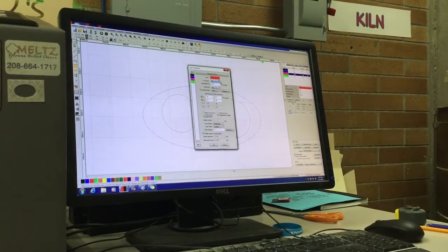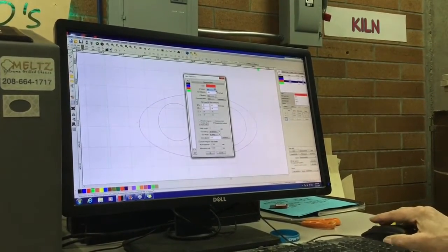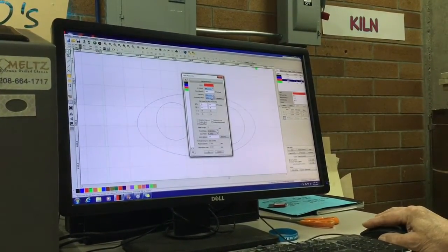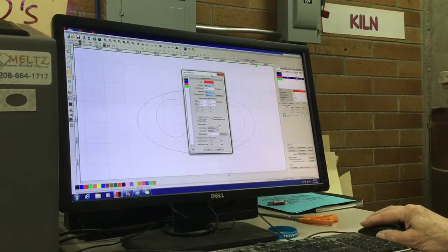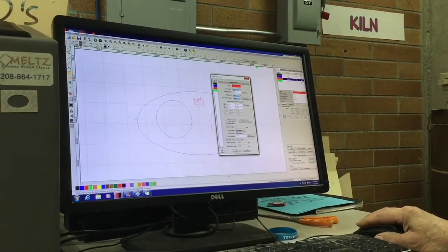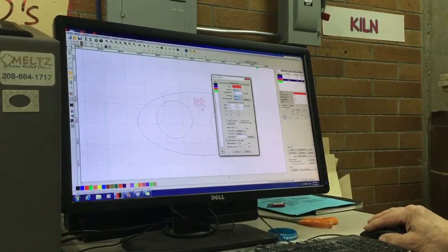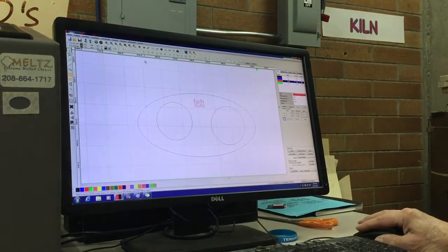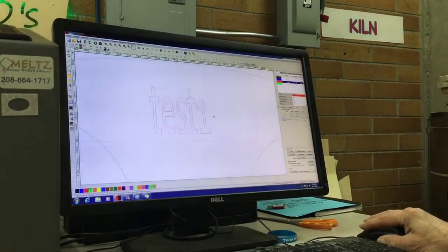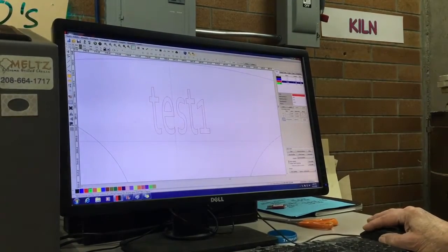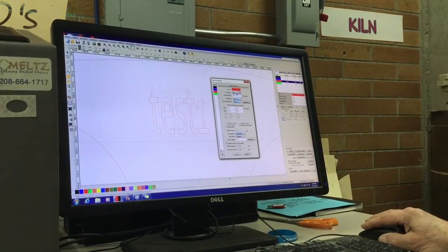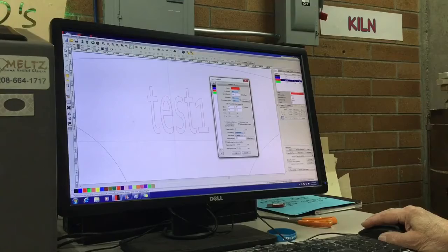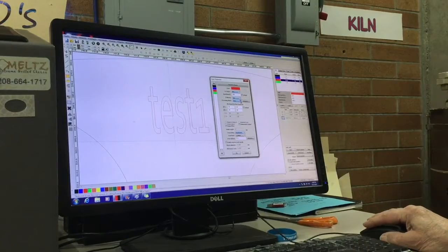When you set it for cut, it just follows the line that you've made. If you set it to scan, then it's going to fill in any closed areas. So if we look at the text, let's zoom in on that. Oops, I need to cancel this. Let's zoom in on the text. Okay. Double click on this to open that up again. So output yes, speed in millimeters per second, we're bumping it up to 200. Blowing is yes. We're using the scan mode.